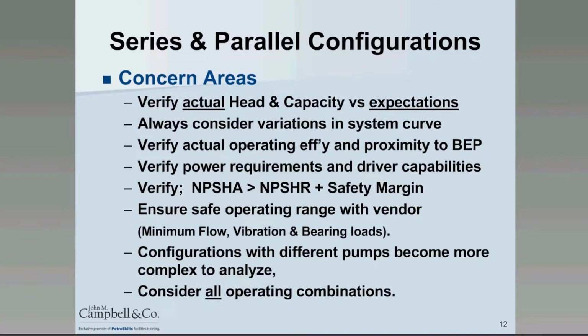Then verify your actual operating efficiency and proximity to best efficiency point so that you can determine horsepowers and establish what your driver capability is. You could see that as we moved into that series pump configuration, that we actually could have overpowered one of our pumps and resulted in driver damage or potential damage to electrical switchgear.